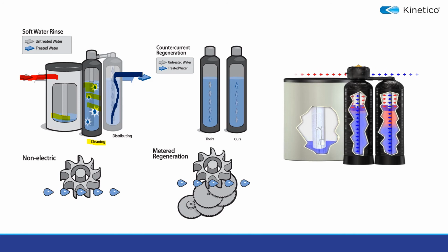As you can see, the water is flowing, and the one tank right now is currently in the process of producing soft water. Water is entering down and going up the riser tube where the second tank is on reserve. As you'll see here, the one tank is now in regeneration, and the other tank is now in operation, serving soft water to the home.